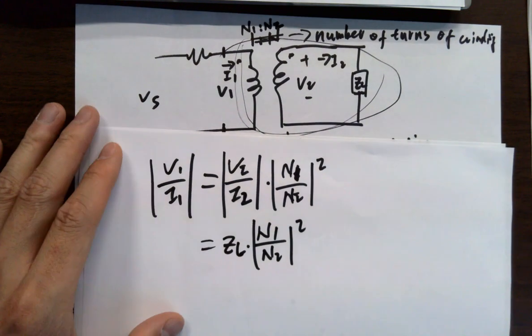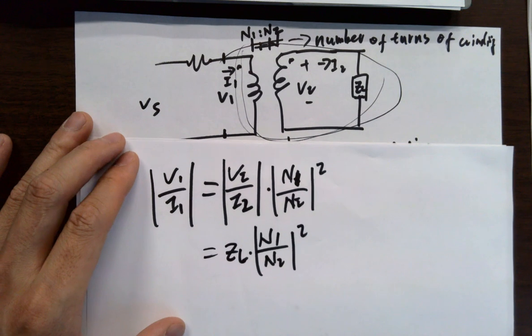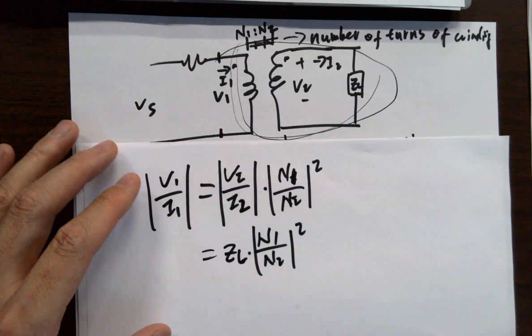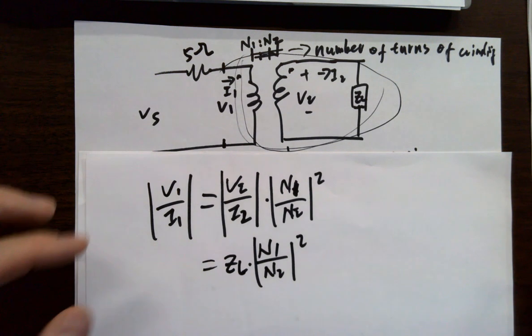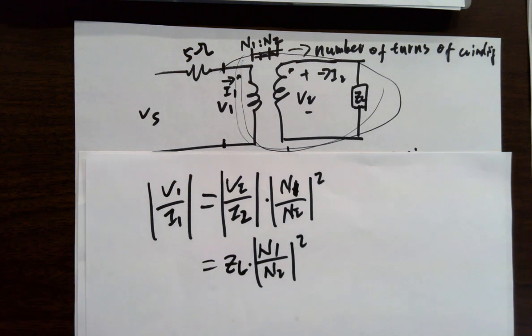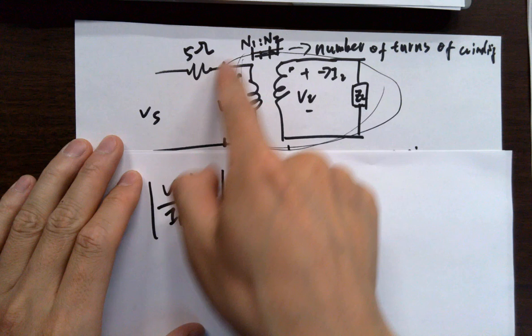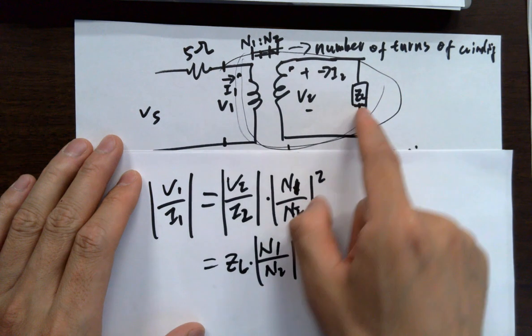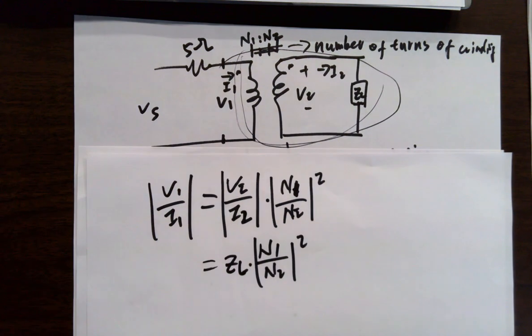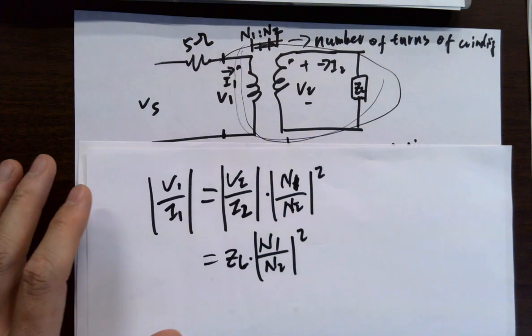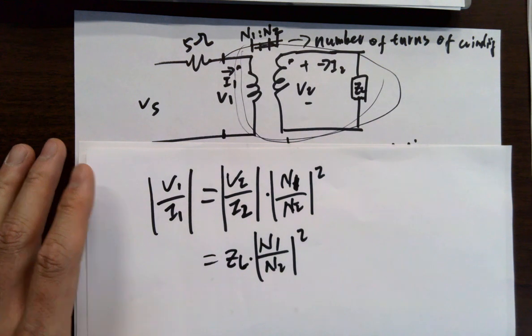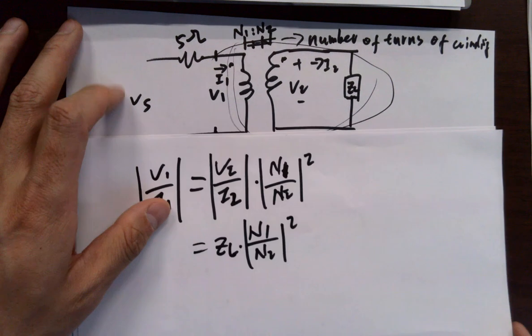Would we normally be finding ZL then? ZL is usually given. Would we find it? Oh yes, sometimes yes. So for example, if I give an R here like 5 ohms, it's going to ask you to find a ZL to maximize power delivery to the load. Because the load is over here, everything over here is the load, right? Not just the ZL, it's including this part as well. So for the maximum power delivered to the load, this part has to equal 5 ohms, right? Does that make sense?